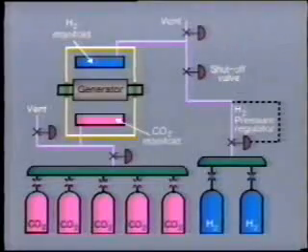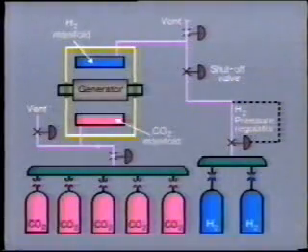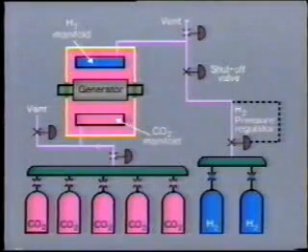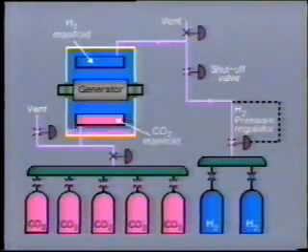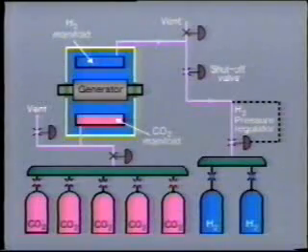When the generator is to be readied for service, then the reverse action takes place. Initially, the generator will be full of air. CO2 will then be admitted at the bottom manifold to push air out from the top. When all air has been expelled, hydrogen will then be admitted from the top manifold, so forcing CO2 out of the bottom. This is quite a tedious process and requires much care and attention from the operator. Make sure that you learn the specific procedures for your particular generator.